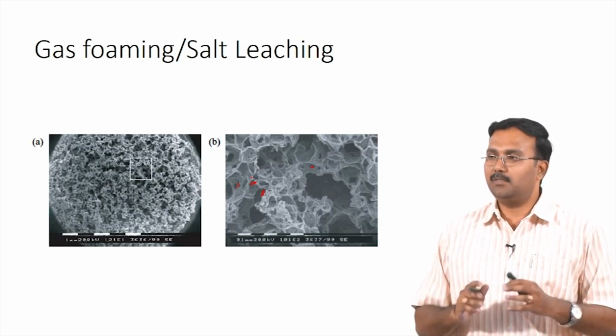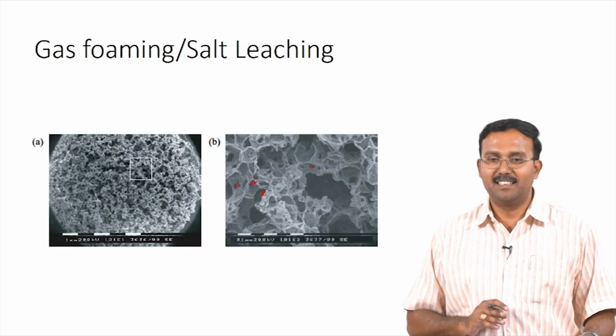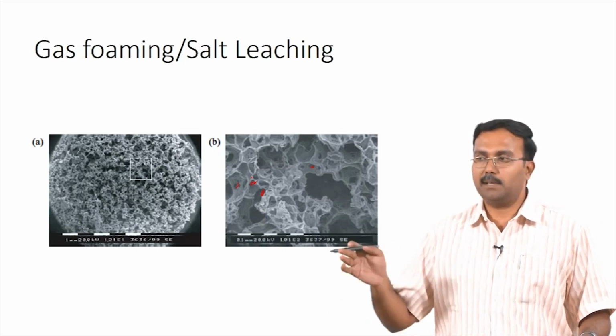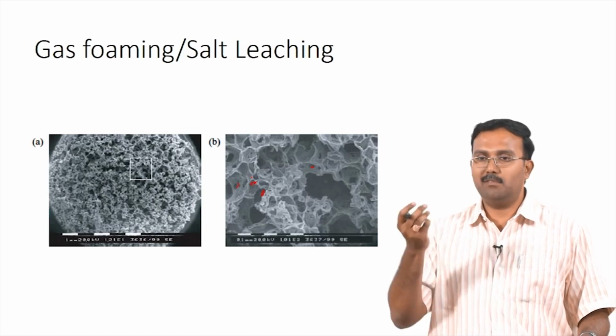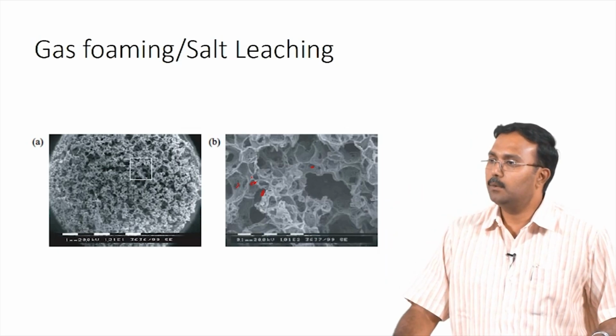Density would be way less for any porous material. If you increase porosity, your mechanical strength is going to come down. As long as you keep increasing your porosity, the mechanical strength will have to come down, right? Because you have pockets of just air. Can you elaborate? What do you mean, accumulation?